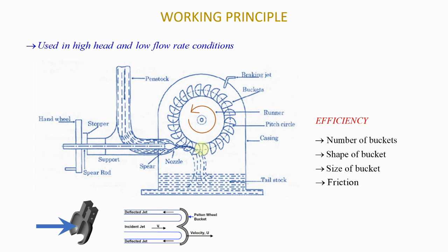And you also have friction that is always a hindrance to our power producing capabilities in mechanical engineering. Whenever you're dealing with a mechanical device, you will always have friction as an issue. And with a Pelton wheel, friction will occur between the water and the air. Okay, as the water is coming out of the nozzle, it will of course interact with the air, and you do have some friction there, and that will of course affect the velocity of the water, and hence the impulse force, and also therefore the power that is generated by the wheel.